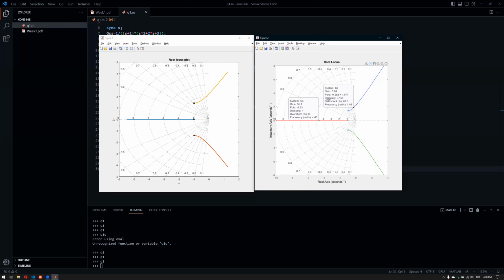It can just give you damping ratio and natural frequency, because the Cartesian coordinate poles are converted into polar coordinate poles. What you see here is basically polar coordinates. If you take the square of the real part, the square of the imaginary part, take the sum, and take the square root, or in other words, just the absolute value of the pole, you will get the natural frequency. And if you get the angle between these two values, the arctan value, this will correspond to a certain slope, and you will get the damping ratio here.